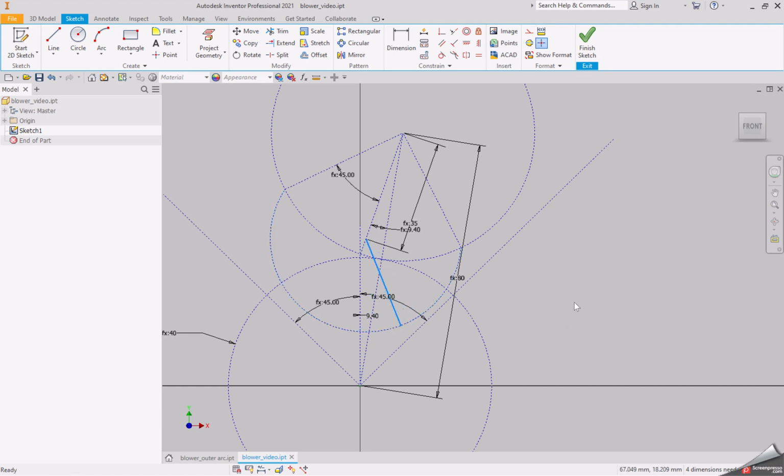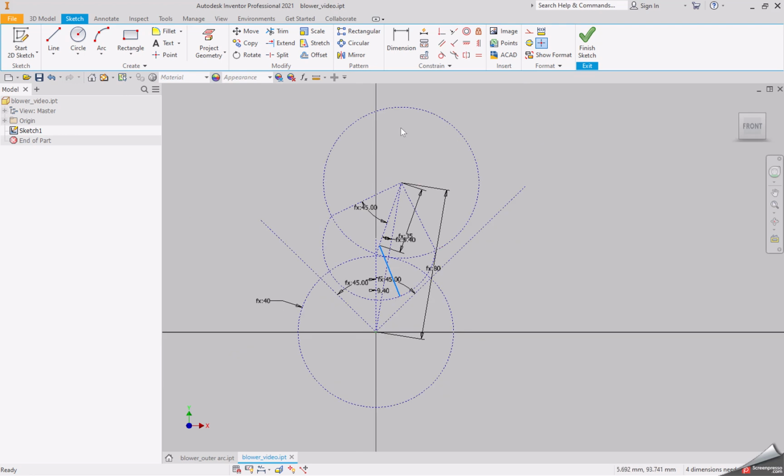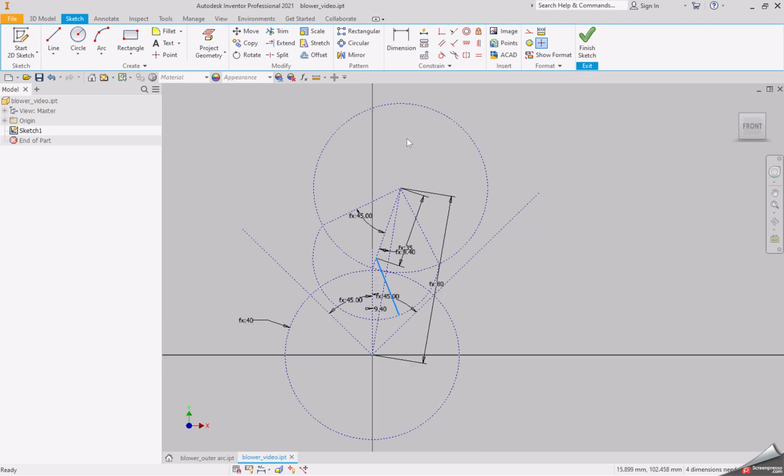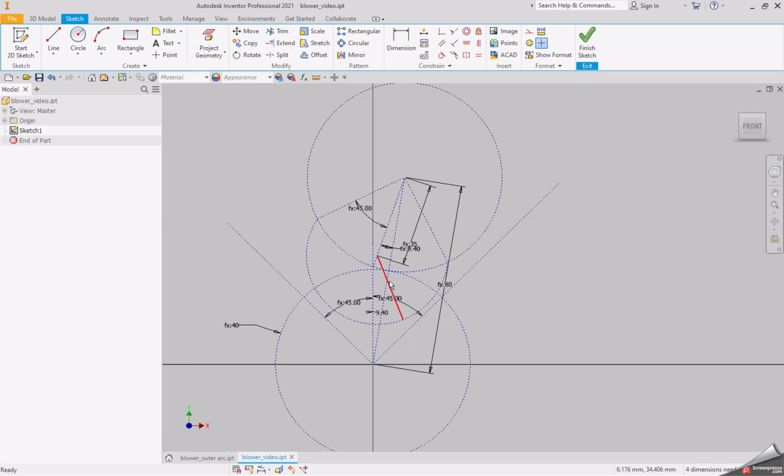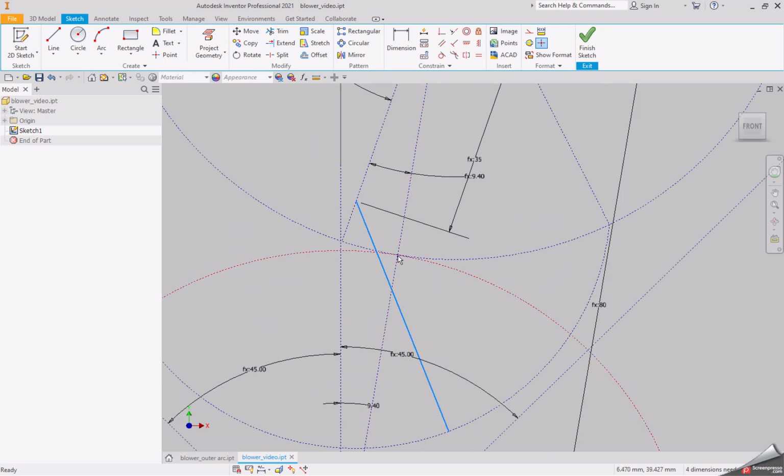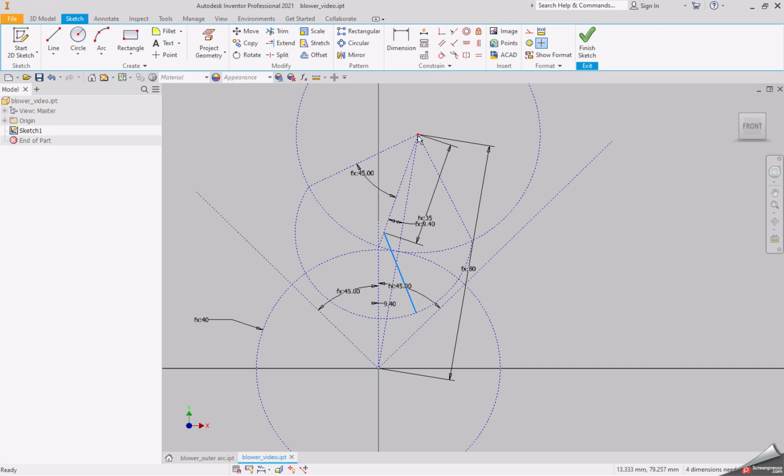So we also know that because these are two wheels that altogether form a, let's say, rolling mechanism, this line needs also to go through a point where the line that connects the centers of these wheels crosses with the pitch circles.